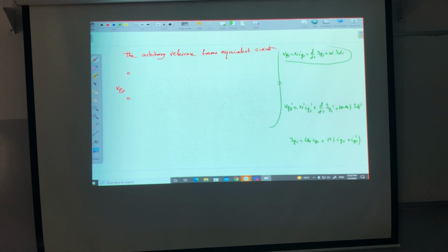So I will try to represent the first one, the voltage equation, VQS, so this is VQS, plus, minus. Now the first thing I will face here is a voltage drop across what? A resistor. So this will be RS, written small. Then I need to represent what? d by dt. So this is an inductor.